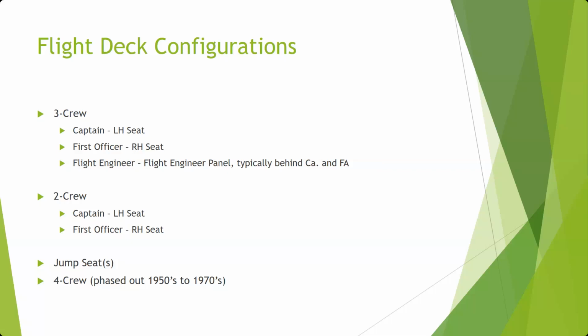Even today, most of the flying done by these aircraft is on autopilot with a navigation system essentially running the show. The crews earn their money when things don't work like they're supposed to. Most of them do hand fly. A lot of them hand fly for takeoff, approach and landing, mainly to keep proficient. But some of your newest, larger aircraft that are what's called Cat 3C qualified can basically do everything from takeoff through landing and rollout without human input, or with minimal human input.